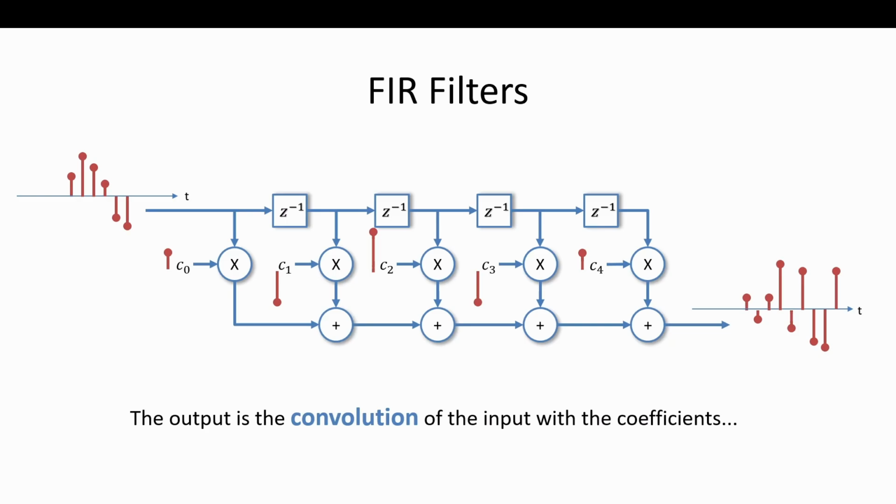So that's what's so handy about having the impulse response and the things we do with it. If we know the impulse response of a system, then from a linear system perspective, when we're working with a linear system, we can predict any output for any input, given the input is a weighted series of impulses. Every one of those impulses is going to move through and create that same impulse response. Then we're seeing a delay and accumulation of weighted impulse responses, and that's what convolution is.